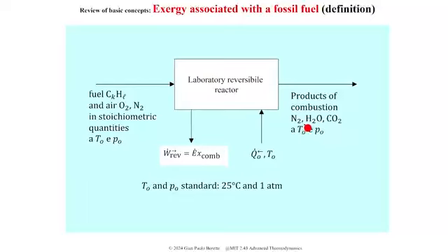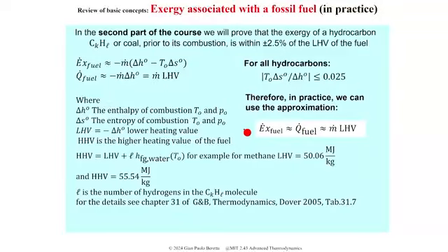So typically, we will see that the exergy of the fuel will be given by this expression. We will define an enthalpy of the combustion reaction and an entropy of combustion.